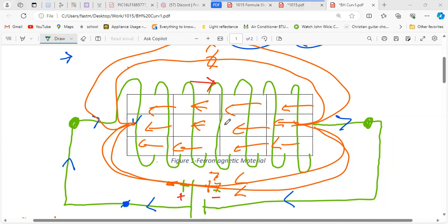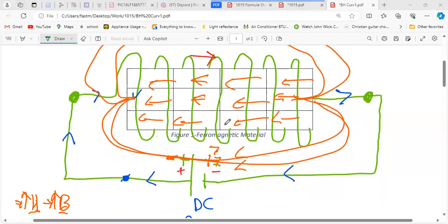When the flux from the primary coil cuts the secondary coil, you have an EMF induced in the secondary coil, and that produces the current, and you get the step up or step down transformer. When I remove the current in the primary, I do not want to still have a magnetic field in my core. I want it to go back to being off, neutral. So you normally use a material that returns to zero, so when I remove the external current, the field goes to zero. It disappears, which is what I want. I don't want flux in my material when I cut off the current.